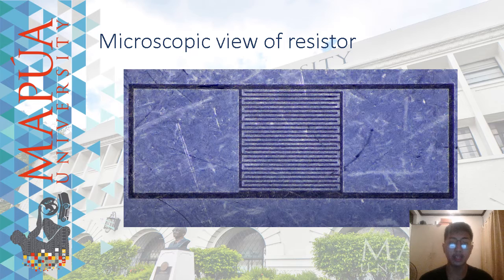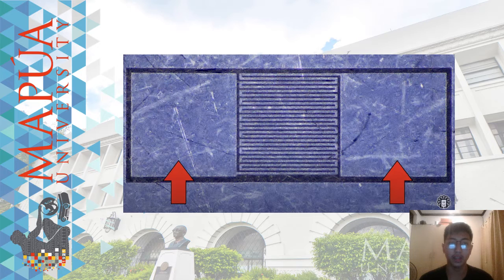This is a tiny resistor. The lighter colored material is actually electrically conductive silicon, and this darker area that's been etched away doesn't conduct. This long winding electrical path forms a resistor, very similar to how long pieces of wire would also have a significant resistance. So if you made an electrical connection between these 2 points, you'd have a microscopic resistor.